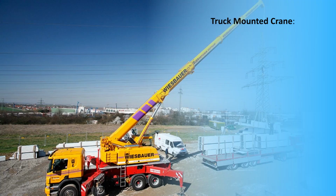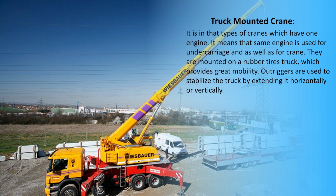Truck mounted cranes. This is a type of crane which has one engine. It means that the same engine is used for the undercarriage as well as for the crane. They are mounted on a rubber tire truck which provides great mobility. Outriggers are used to stabilize the truck by extending horizontally or vertically.